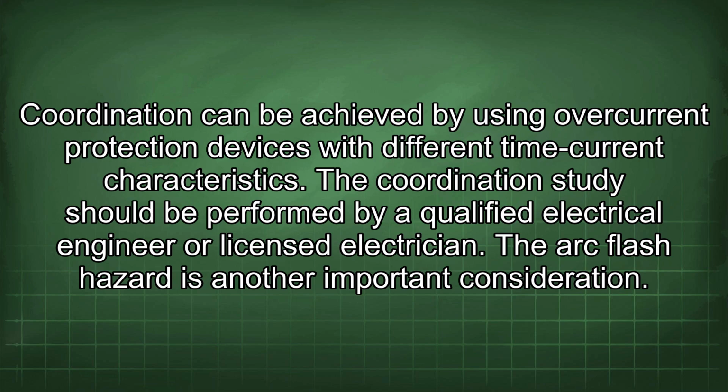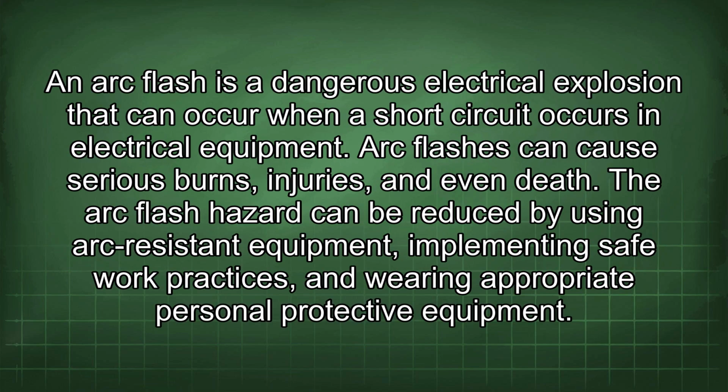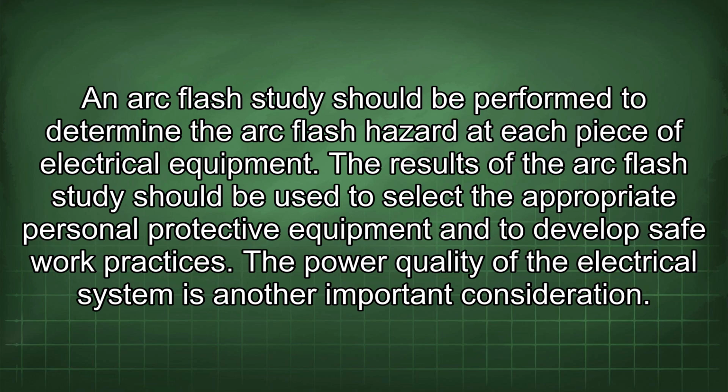The arc flash hazard is another important consideration. An arc flash is a dangerous electrical explosion that can occur when a short circuit occurs in electrical equipment. Arc flashes can cause serious burns, injuries, and even death. The arc flash hazard can be reduced by using arc-resistant equipment, implementing safe work practices, and wearing appropriate personal protective equipment. An arc flash study should be performed to determine the arc flash hazard at each piece of electrical equipment. The results of the arc flash study should be used to select the appropriate personal protective equipment and to develop safe work practices.